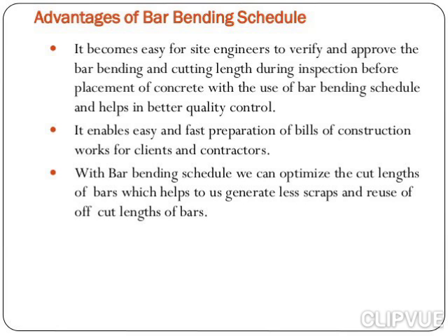It enables easy and fast preparation of bills of construction works for clients and contractors. With bar bending schedule, we can optimize the cut lengths of bars, which helps us to generate less scraps and reuse of cut lengths of bars.